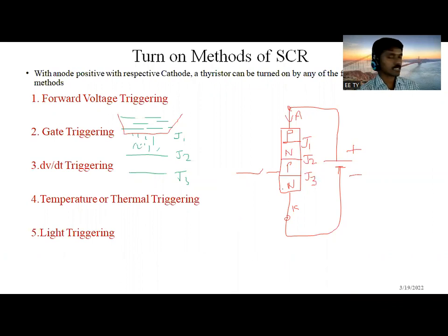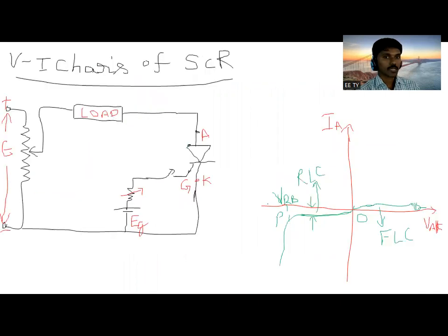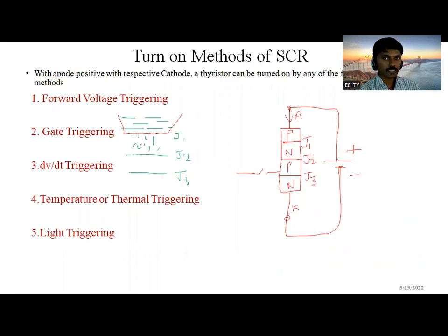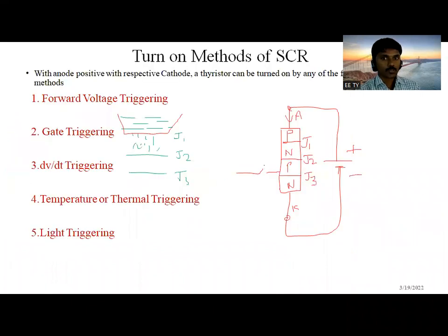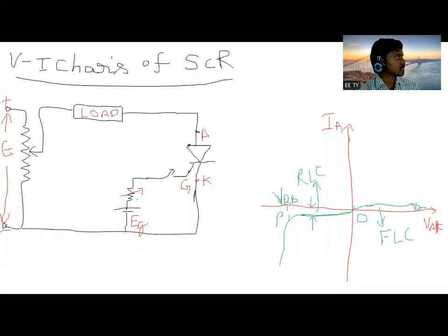Yes. Exactly. Same condition: anode should be connected to the positive supply, cathode should be connected to the negative supply. So like this. Anode is connected to the positive and cathode is connected to the negative. Is it clear? I have drawn this in the diagram, both are the same. Are you got? Okay. Next, some amount of voltage is applied to the gate circuit. The gate switch should be closed. So here we applied voltage to the gate also. Clear? This is the condition.